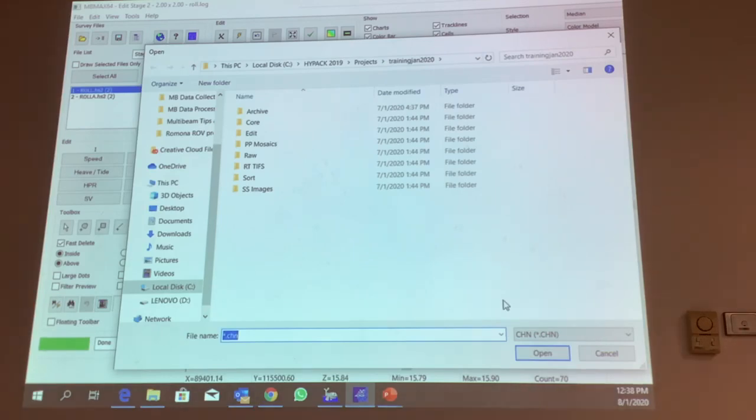Also, very important is when you are importing the channel design, you must see the depth, whether it's positive or negative. Because sometimes your multi-beam data, if it's by elevation or depth, if you do it wrong, then when you import the channel data, it will look like it's very far, or it's above or below the data. But it can be imported from AutoCAD file.